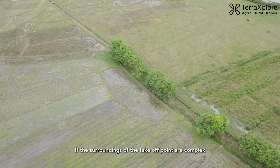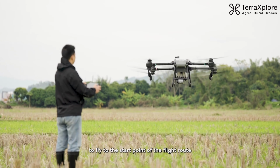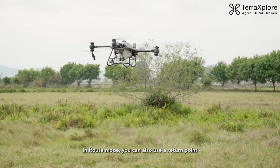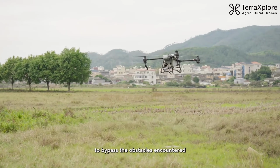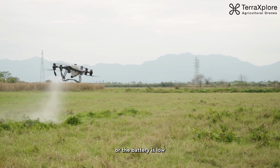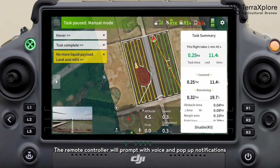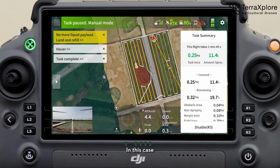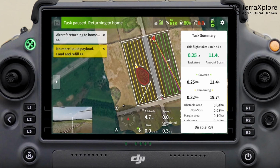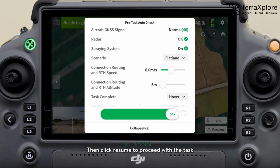If the surroundings of the takeoff point are complex, we recommend that you manually control the Agras drone to fly to the start point of the flight route before starting the task. In route mode, you can also use a return point to bypass the obstacles encountered. When the liquid pesticide is used up or the battery is low, the remote controller will prompt with voice and pop-up notifications. In this case, control the drone to return to the takeoff point for refill or battery change. Then, click Resume to proceed with the task.